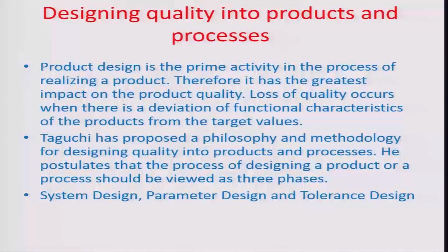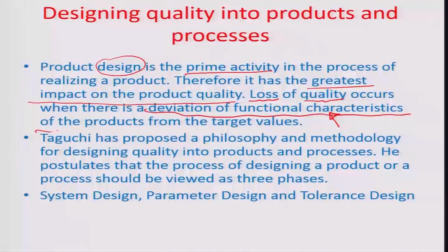So, when we look at product design, it is a prime activity in the process of realizing any product, and therefore, this design really would have the greatest impact on the quality of the product. And whenever there is a deviation in this quality, there is going to be some kind of loss associated with such deviations. Although this loss does not really come on a balance sheet, these losses are notional, and if these losses come in, it gives you an idea about how to proceed, so that you can do some loss minimization. Some numbers are there rather than just qualitative indices, and therefore, it is a very good strategy to monitor the deviation of all the functional characteristics of products from their target values through adding notional losses to quality.